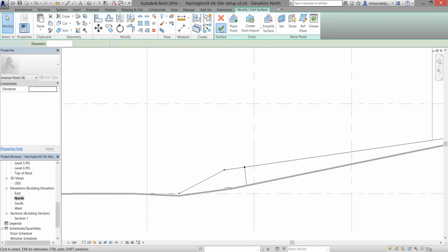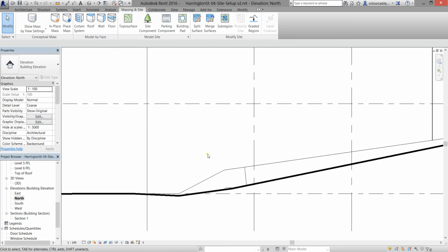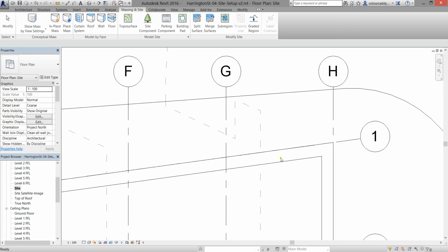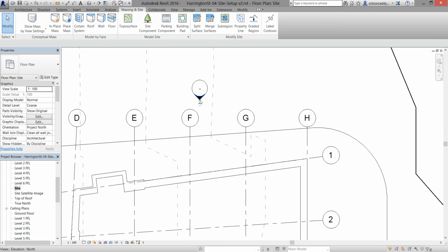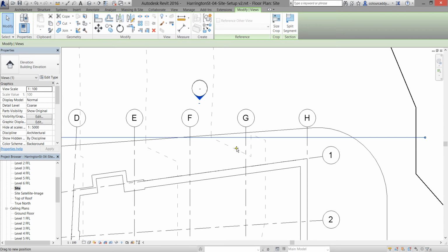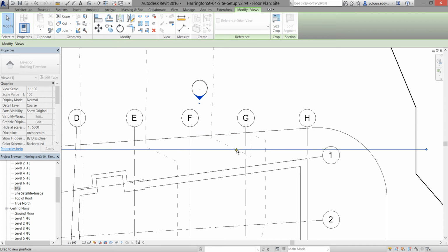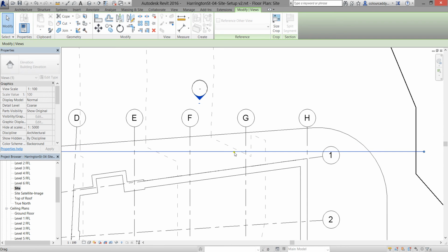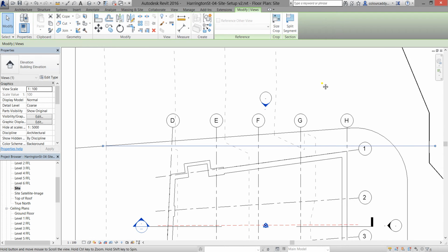Now if we want that to show in the elevation as the line that's being cut, the ground line in other words, then all we need to do is go to here. So there's the elevation symbol. Clicking on the arrow you can see the line of that elevation. So I'm going to leave the symbol there, but I'm going to bring that line down to where the stairs are. So no one will see this on the drawing, but we'll know where it is.